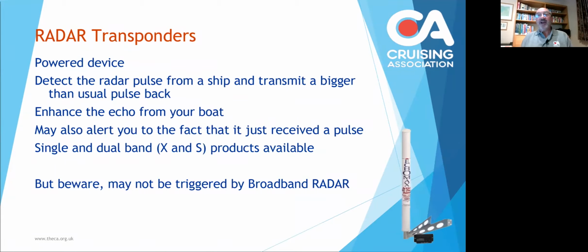Now you can also have a radar transponder, which is a powered device. So it takes power from usually your 12-volt system. It will detect a radar pulse coming from a ship and then transmit back a bigger than usual pulse. So it enhances the echo from your boat, makes it more clear that you are there, makes your presence more obvious. Some of them may also alert you to the fact that you've just received a pulse.